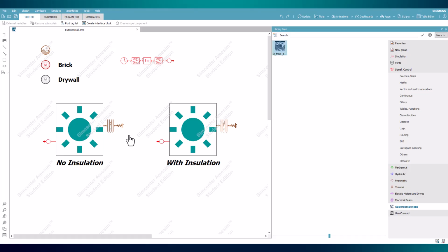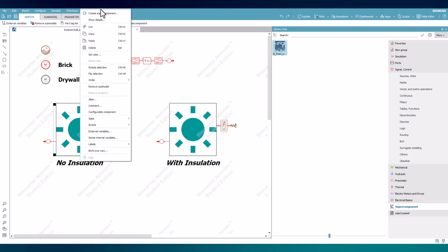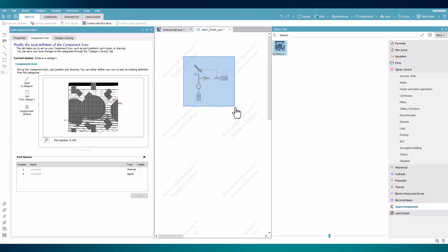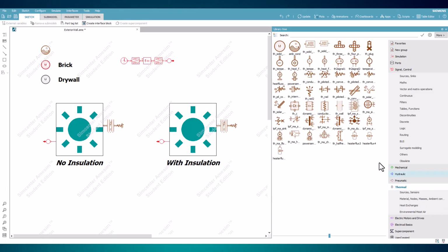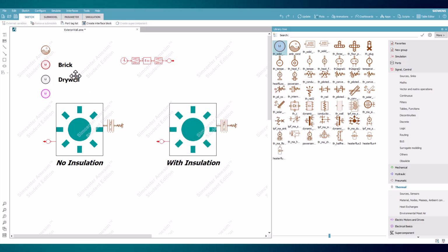Because the sun's radiation and convection behavior are not of priority for analysis, the components were compiled and placed into a supercomponent, created and saved into a library through the supercomponent tutorials whose links are also in the bio. Opening up either, you can see those heat transfer components within that still have the same parameters. More additions are labels for each of the models to differentiate which thermal wall component will include insulation. The last addition must be made to add a thermal solid properties component for the insulation. Once added, we can move to submodel mode.